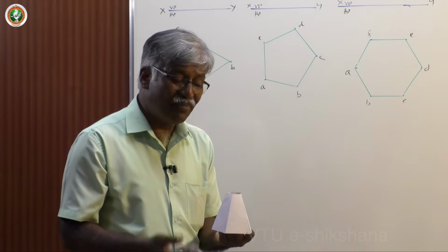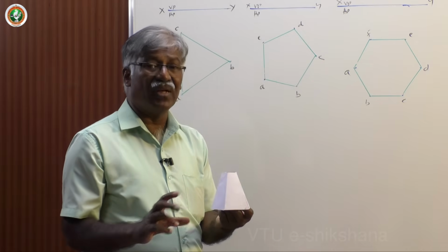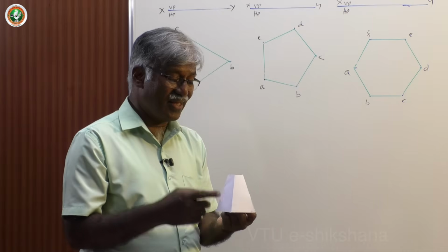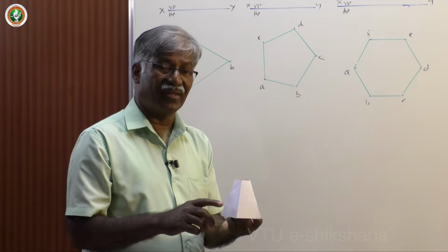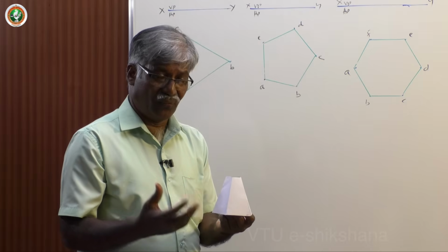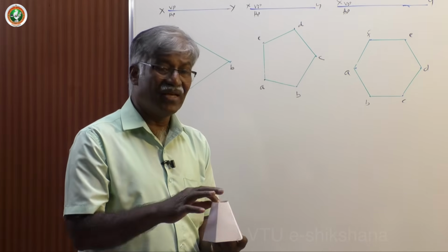And if there are multiple figures of the same type, you need not go for multiple figures. Just draw one figure and try to scale it. You know very well that the size, say 40, this is 25 or 30, whatever, you can scale it and start working. So if the situation demands, then draw top and front views. Otherwise, you just draw only the shape, that's all.